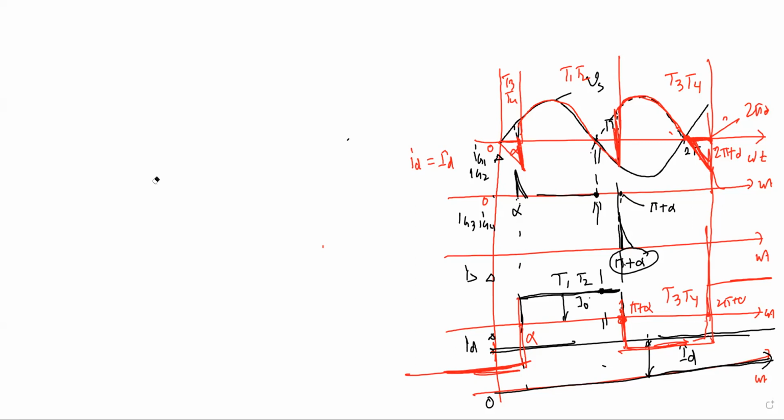That is why there is a term we call dead time. Practically, when you implement this kind of circuit, you must make a delay here. There must be a delay. We call it dead time. You must maintain a dead time, as you mentioned that it is always conducting. So you have to make somehow a delay so that the circuit is not short circuited. You understand it or not? Yes, sir. That's why I was asking.